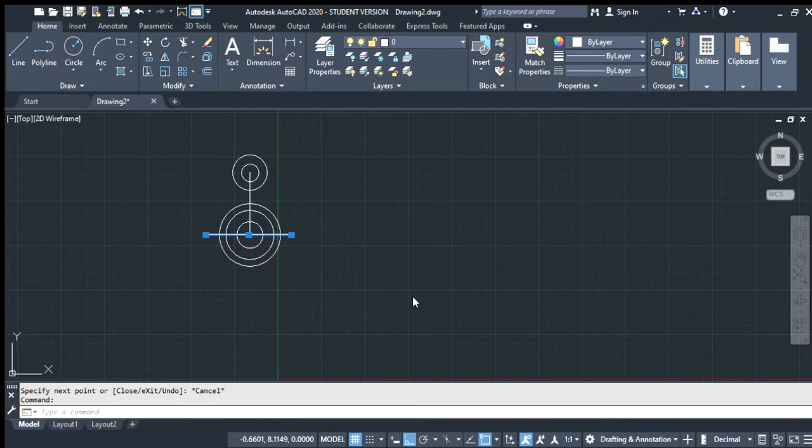I'm sure you can't see the pop-up that I've actually right clicked right now. The recording device I'm using doesn't allow that. But when you right click it, it'll give you your pop-up, and under it you'll see one that says draw order. You do send to back, escape again, and when you select it the next time, you'll select that half line. I'll go ahead and delete it, and now I have a perpendicular line that intersects my circles.